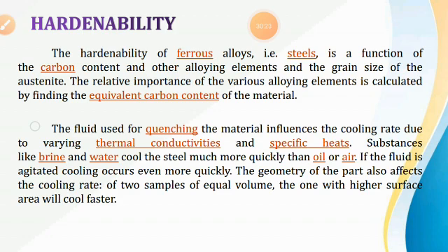Hardenability depends upon the shape, geometry, method of cooling, carbon content and grain structure, and these are all directly related to hardenability.